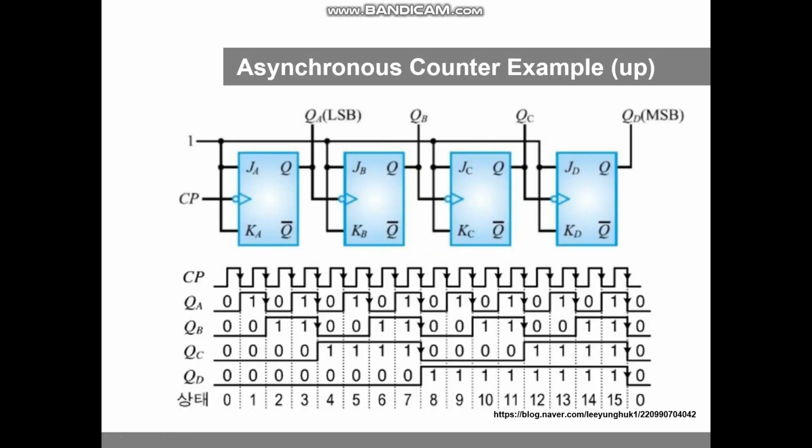The counter is a logic circuit for counting the number of clock pulses. Such counters are synchronous and asynchronous. The synchronous counter has all flip-flops connected to a common clock so that all flip-flops are triggered simultaneously. Asynchronous counters are also called ripple counters.